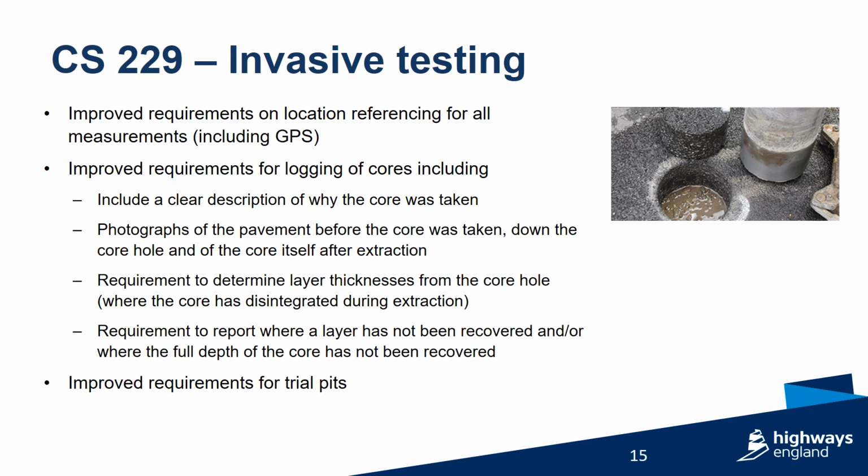Invasive testing includes coring, the dynamic cone penetrometer test, and test pits. To improve the clarity and usefulness of the data, the new standard has enhanced the requirements for referencing. It is now a requirement to carry out GPS location referencing for each test using a GPS device with an accuracy of better than 1 meter.